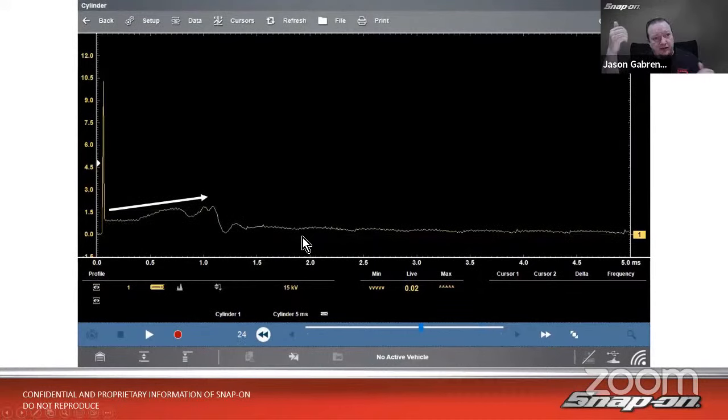So I started pinching off the fuel line coming off the fuel filter under the bay. And you can see where it's flat, and then all of a sudden it goes up at the end. And then it almost stalled, actually. So you can kind of see a little bit of that going on there. But it's flat because it has enough fuel. Once it starts running out of fuel to burn, we'll see that nose up at the end go up. All right, so that's an example of a lean condition, how it kind of goes up at the end.